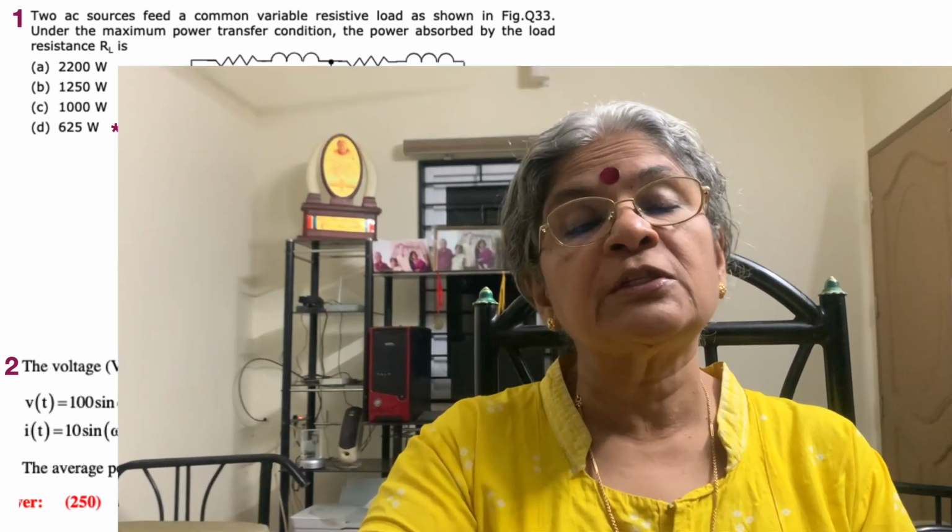So as a 4-step version, I hope it's clear to you that you find out the Thevenin's impedance, call it the resistive value, 5 ohms. Then find out the Thevenin's voltage. How do you do that? You open out RL and find the drop across 6 plus j8. Deduct it from 100 angle 0, or you can go from the other side and you'll see that it is equal to 100 angle 0.